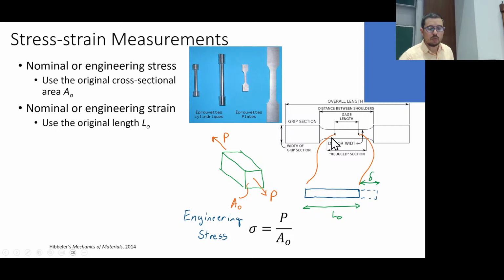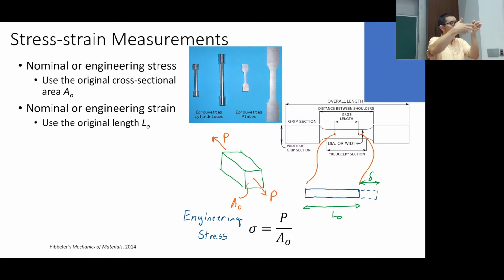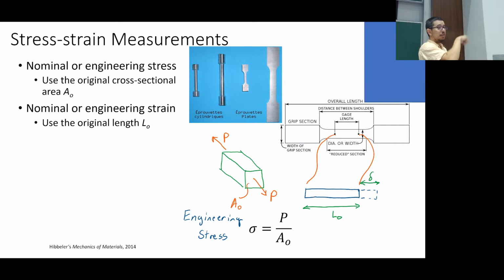And what you would do, sometimes there are little probes that you put right on the material itself. You attach them, and they are very sensitive, and they'll be able to measure very, very minute changes. We're talking hundreds, if not less, of microns. And sometimes people paint dots on it, and they use what's called digital image correlation, and they have a camera that's able to calculate the very precise small motion as well in your test region. Okay? And the machines that, yes, question.